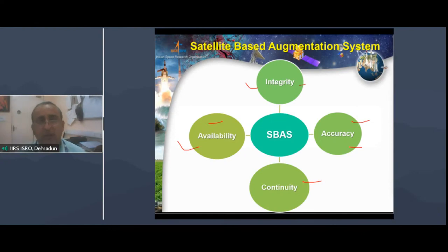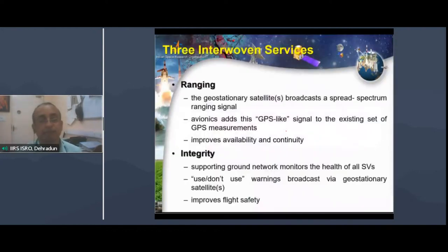By default, without doing anything, we get the data of say 4 to 5 meter best accuracy. That means there is 4 to 5 meter error in our XYZ coordinates. But if we incorporate SBAS facility, that is basically GPS corrections through SBAS, the error will come down to 1 to 2 meter without doing anything, just applying these corrections through SBAS.